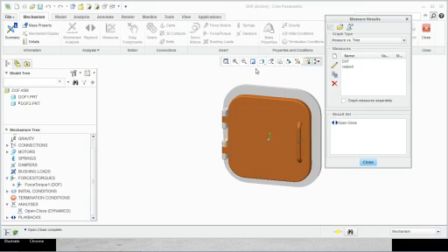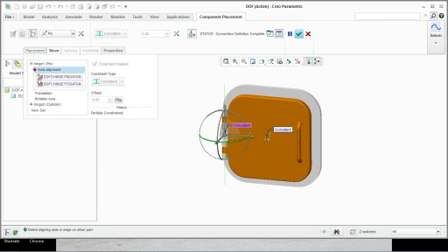Let's go back again. And right now, I'm going to go ahead and enable this. This is the common mistake, top and at the bottom. So we go ahead and enable it. All right. So now notice it has 2 connections, which makes it do the same thing. So now I go into mechanism. And I'm going to try and run that analysis again.